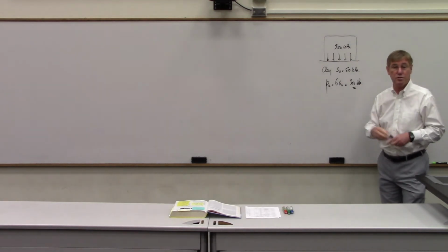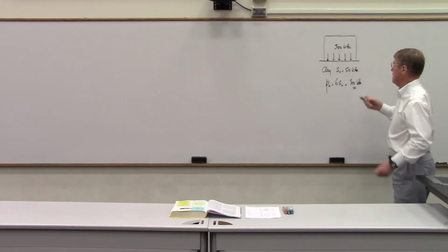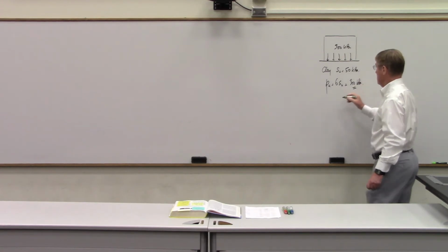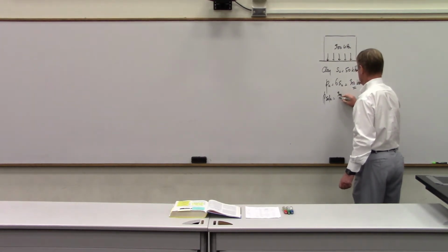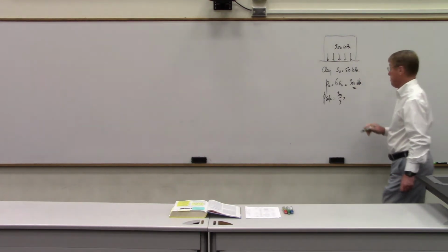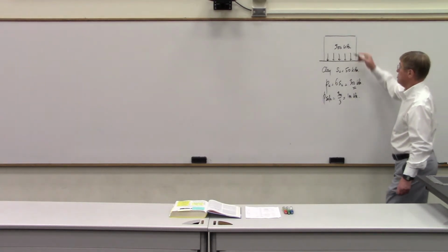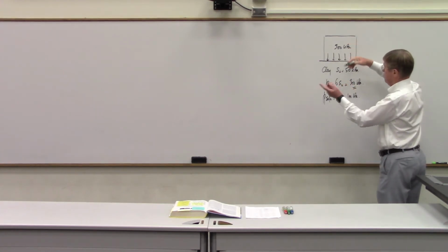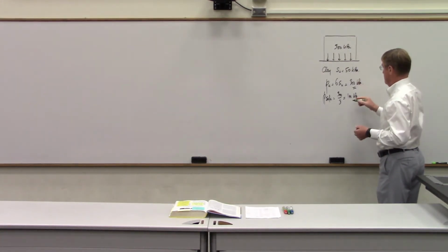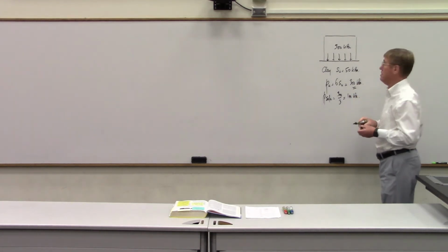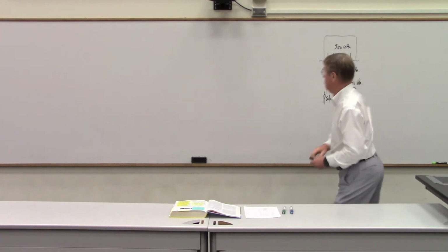You put 300 kilopascal of pressure, boom, you get a failure. Today, we would consider 300, and we would do P safe equals the ultimate pressure divided by a factor of safety, let's say 3, and that would give us a safe pressure of 100 kPa. We would consider the weight and say weight of 20,000 tons divided by the length times the width gives us 100.